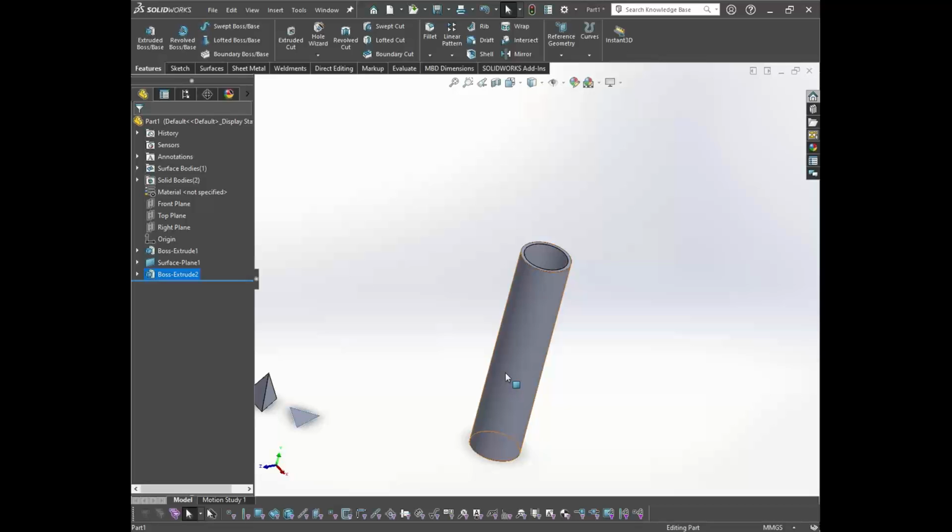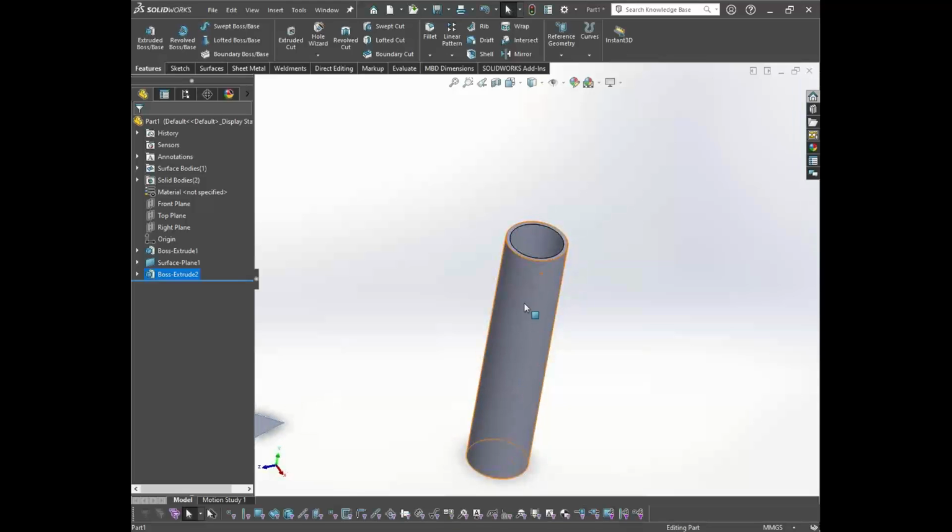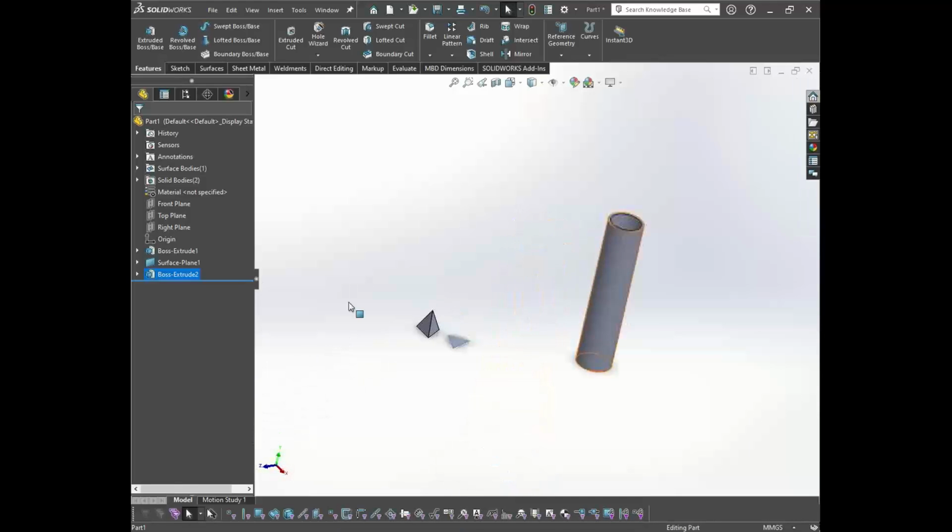Meshing size is directly proportional to the time for solving. The more elements involved in your model, the more degrees of freedom there will be to solve. Accordingly, the model will take much more time to solve. So when I'm considering this beam element, it will have only two nodes at the end, as shown in